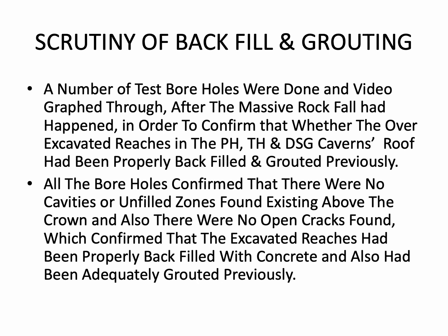All the boreholes confirmed that there were no cavities or unfilled zones existing above the crown, and also no open cracks were found, which confirmed that the excavated reaches had been properly backfilled with concrete and also had been adequately grouted previously.